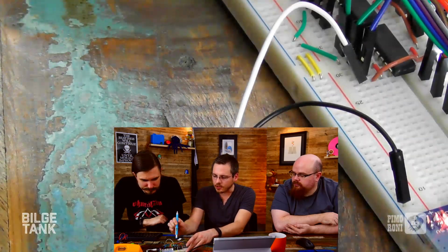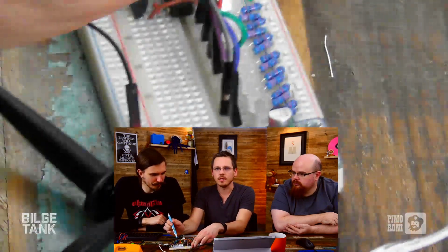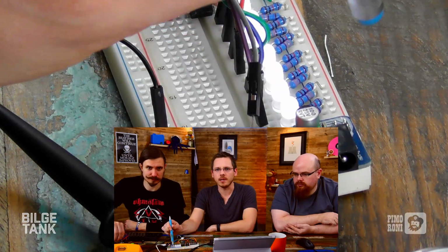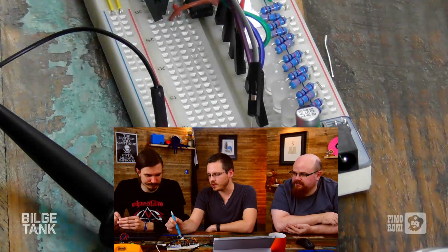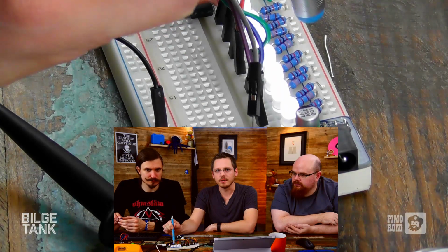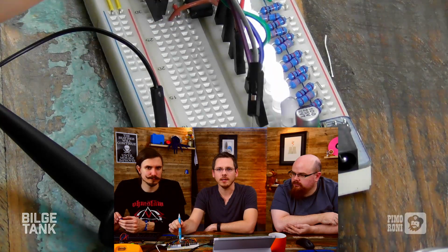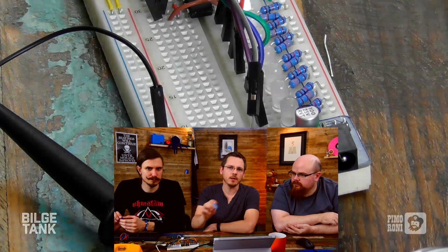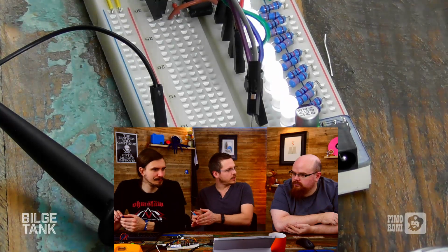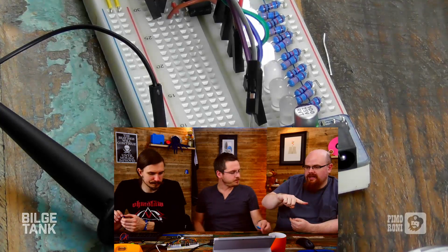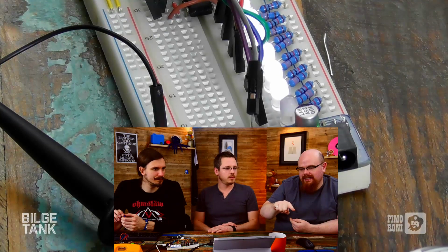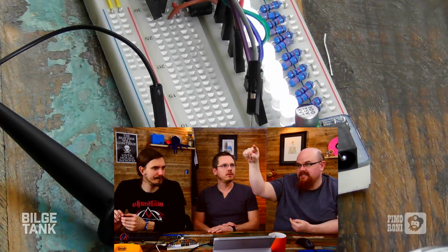Yep. And then the comparator outputs are just mapped over to LEDs, so there's nothing particularly complicated here, but each LED's got a current limiting resistor, just because we're sensible like that, and a pull-up resistor as well, which the comparator outputs need. But there you can see the 8 discrete steps of the ADC working, and what we're actually feeding in is a perfect sine wave. So you can see how the system breaks that analog signal down into discrete digital chunks. Something that looks like that on the oscilloscope actually ends up looking on the LEDs like a set of stairs going up and down.